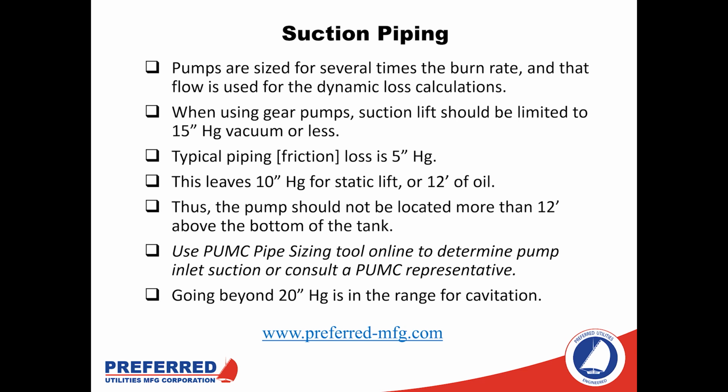And that's because with positive displacement pumps that are quote-unquote self-priming, that section of piping will generally be under a vacuum, whereas the rest of the system will most likely be under positive pressure. And if you've ever worked with any sort of a hydraulic or hydronic system, something that's under a vacuum can pose a lot of issues.